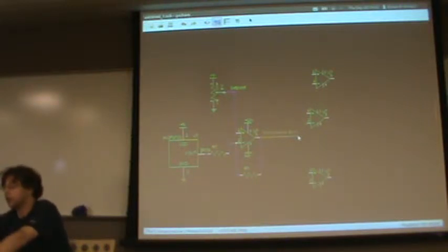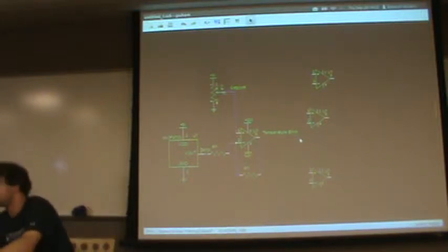So, one thing, it tries to be helpful. Whenever you see that little circle there, that means that when you drop the wire, it'll automatically connect it. That is often a really big pain in the ass. So if you hold down the control key, it'll go away and it'll go where you actually want it. Took me a while to figure that one out. It's a useful tip.